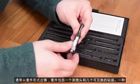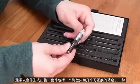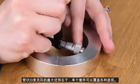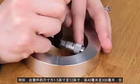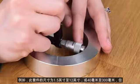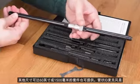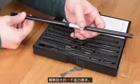For more accurate measurements, you might consider tubular ID micrometers. These are usually sold in kits that include a micrometer head and several interchangeable anvils. A big advantage of tubular ID mics is that a single kit can cover a wide range of diameters. This set, for example, can measure from 1.5 inches to 12 inches, or 40 millimeters to 300 millimeters, but other sets are available that can measure up to 60 inches or 1,500 millimeters. Tubular ID mics are accurate to about 1 thou or 25 microns.